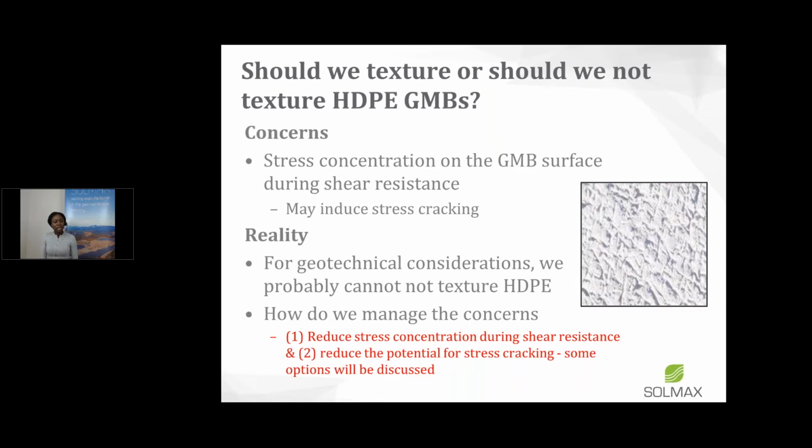And he emailed me and said, are you going to mention to the industry not to texture HDPE geomembranes? His position was that as the textured HDPE geomembrane is doing its job, as the textured surface is trying to resist the movement, we may be creating stress concentration on the surface of the geomembrane that may induce stress cracking.